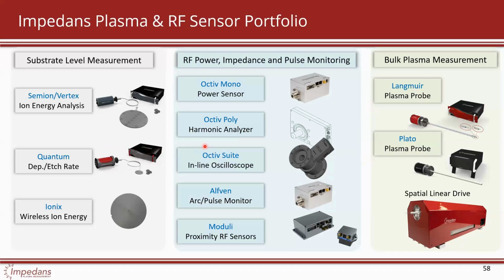With the RFEAs, it's manual. With the Langmuir probe, there is an additional trigger port, which allows you to start a scan with an analog signal. You can send a voltage spike and it will do a scan at that exact moment. The scan preps and then it's ready to go. So the Langmuir probe has a slightly different way of doing that. I hope that answers your question.